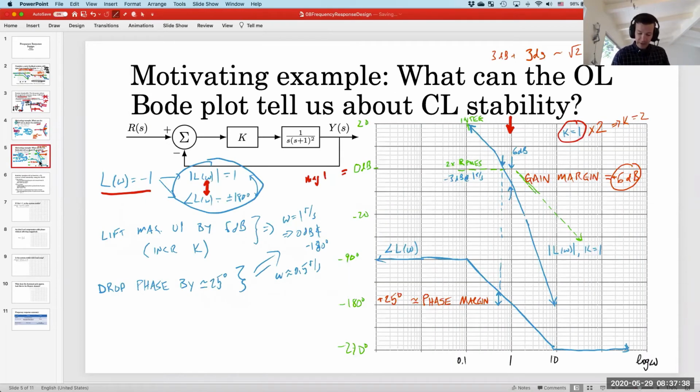So this is a kind of motivating example. It's almost better, I would say, than root locus, because we get quantifiable margins here. If I pick a gain, so again, this whole thing started when I picked k equals 1, once I pick that value, everything is then fixed. And if I draw the open loop Bode plot, I can then measure how far away from unstable the closed loop system would be. That seems like a powerful tool. I hope you recognize that.